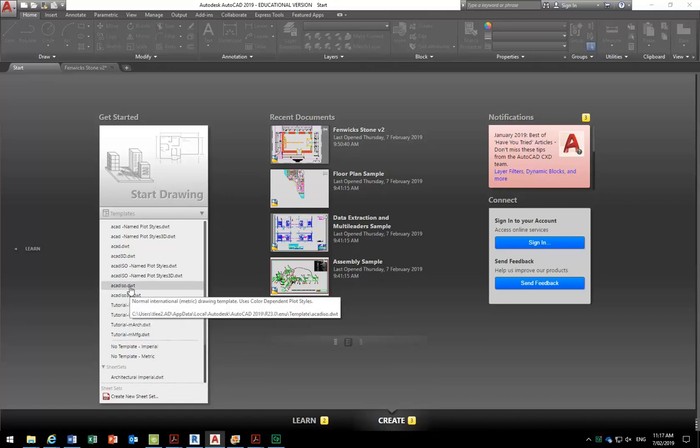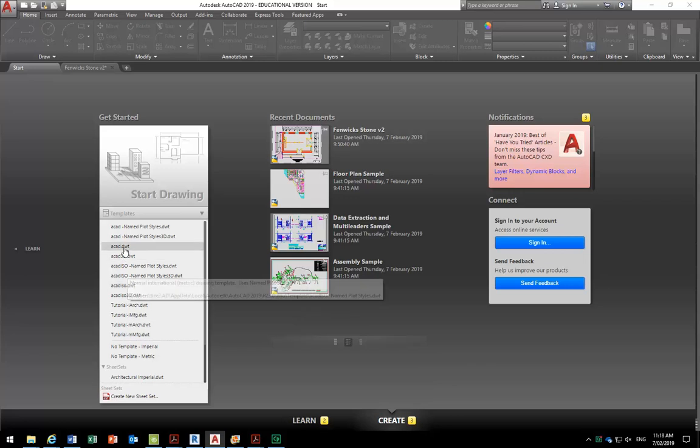So these are the starting settings for your files. And, well, I'll just put it out, there are two main options. Some people use AutoCAD. That works for metric and imperial. You can see there it does say feet and inches. It is more set up for imperial. So the better option is AutoCAD ISO. So that's probably the one you should use 90% of the time.